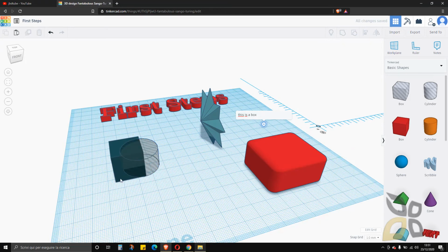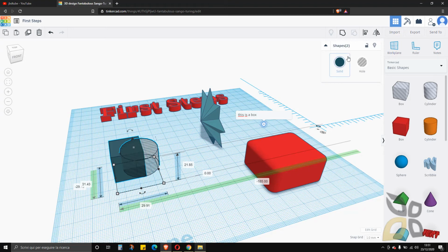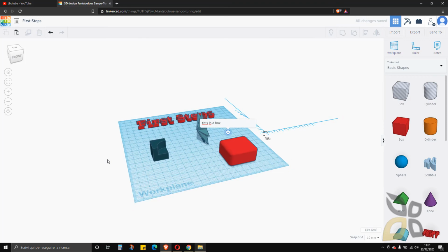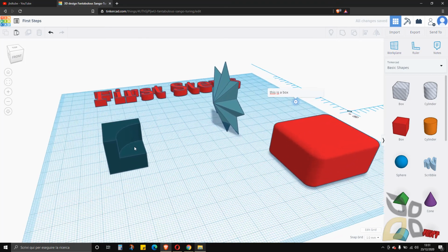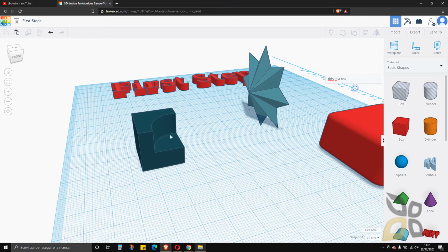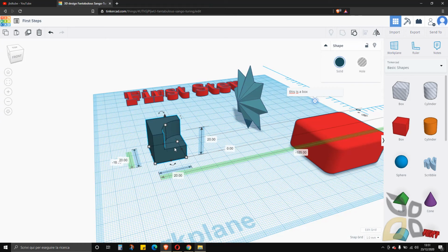So this becomes transparent, and let me show you what happens when I create a group. So I would select these two again, and again I want to create a group like that. But alright, so basically what happens is that the cylinder has gone away, and also part of the box has gone away with the cylinder. So the cylinder is still there, it's invisible, and it's doing this operation, which is called a Boolean operation. So it's a subtraction from the original box. And you can do this with all the shapes that you find in the libraries.